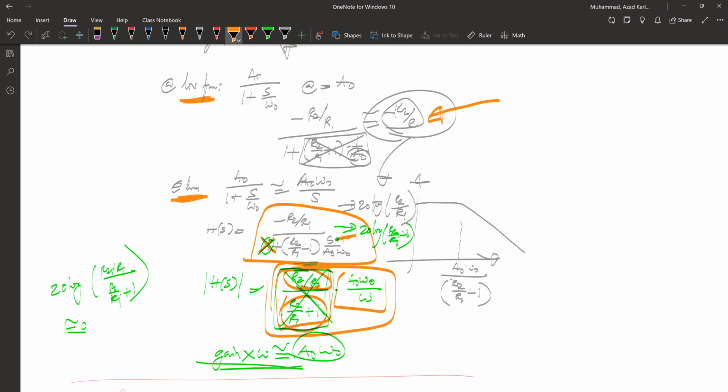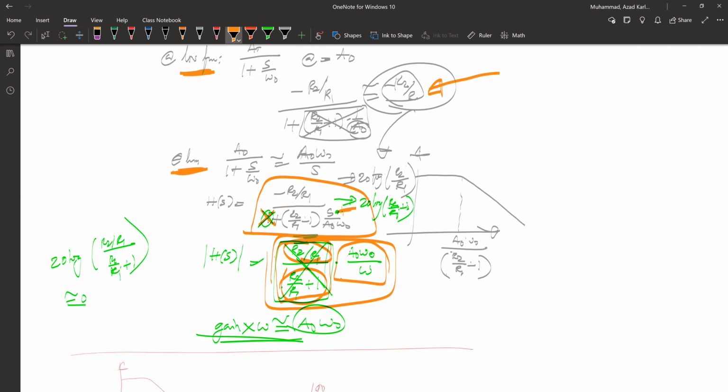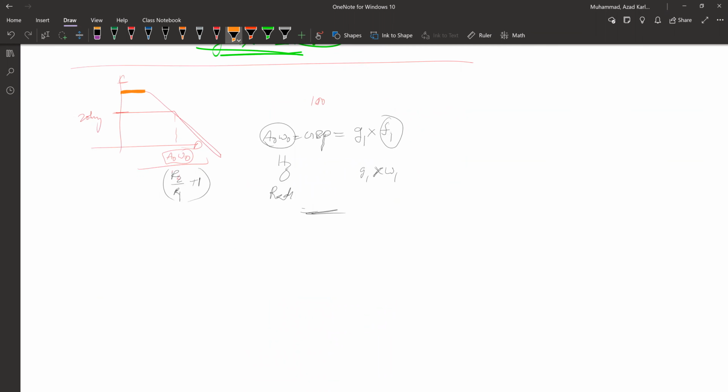So this looks pretty similar to what we have for the non-inverting case, right? All we have to know, in conclusion, is that if you know the open loop op-amp's Bode plot and you're trying to build an amplifier of a specific gain, you already have access to the frequency because you already know the gain bandwidth product.